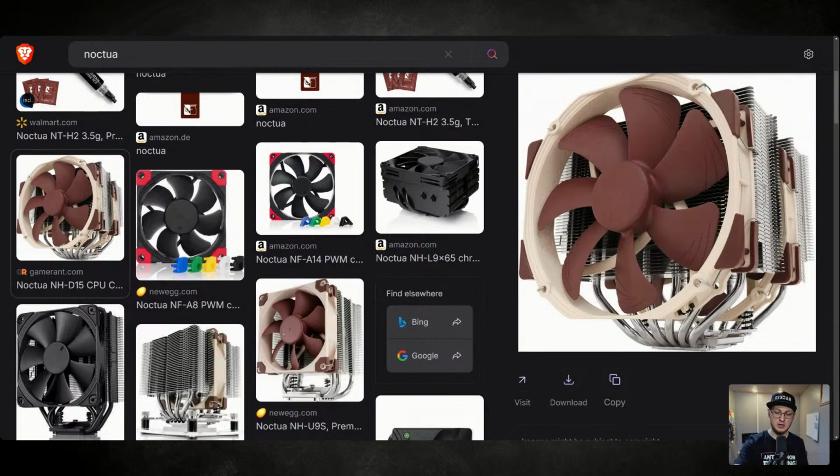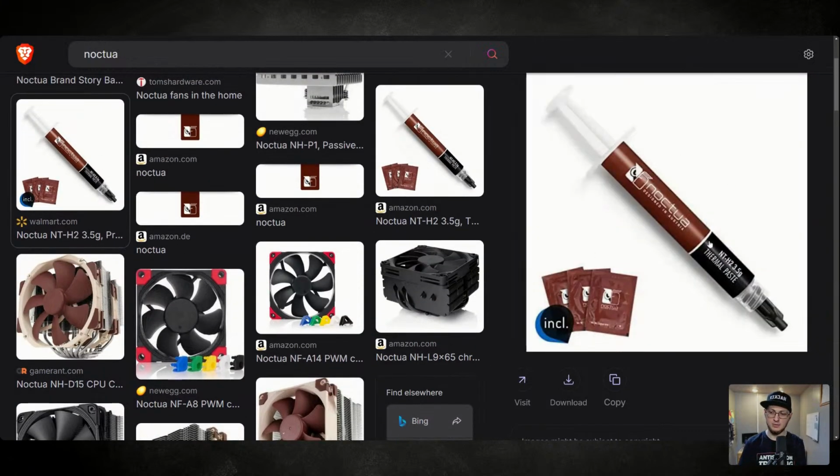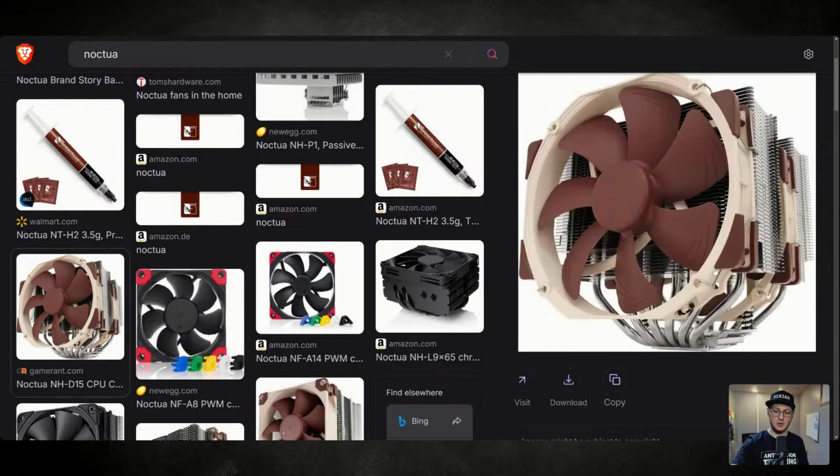It's going to attach to the top of your processor itself. Typically, you'll have thermal paste that goes in between the two, which you'd never want to use too much. Definitely watch a video on it, especially if it's your first time doing a build. You want to be very careful with the thermal paste. There's a certain pattern you want to put out, and you don't want to use too much or too little. Then you see these fins and everything else here. These are heat pipes, which are designed to take the heat and move it upwards into these fins. This particular model also has fans built onto it to take that heat away from the metal itself. So this is just one example of that.